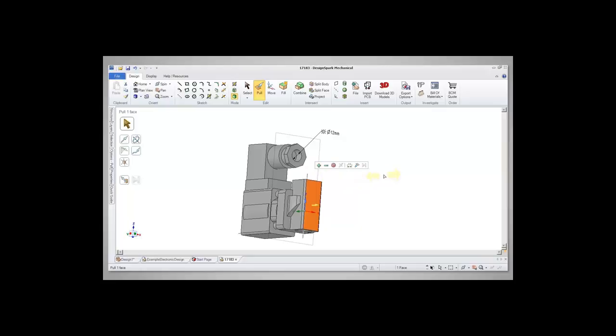Within the software, there are a number of ways to get help if you're not sure about anything. Firstly, you can hover the cursor over the tool or guide you're curious about. This will bring up a tip, as well as offering access to context-sensitive help. For example, hovering over the spin, pan and zoom tools in the Orient group will show a tip including the shortcut details for that tool.